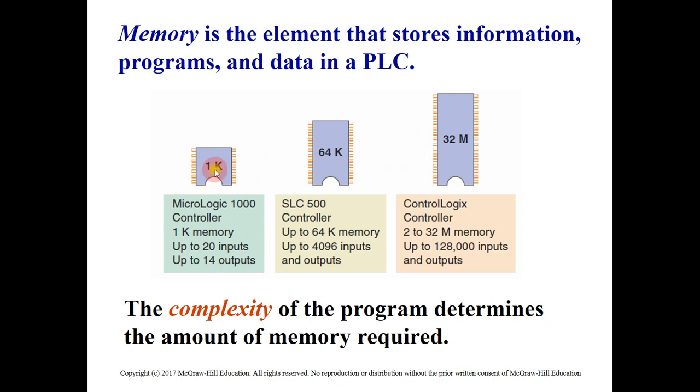The size of memory actually depends on two main things. One is the number of inputs and outputs that will be connected to the PLC system. The other is how complex the program is that we are going to use to control the process.